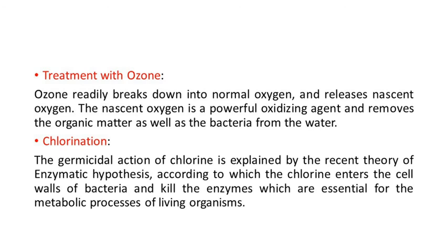And the opposite: suppose the water gets more than the required dose, it changes the taste and may change the odor of the water. Suppose your requirement is 2 ppm, and in that case you add 3 to 4 ppm, that is an excess of the 2 ppm dose. If you add an excess dose, it will change the taste of the water, sometimes the color of the water may also change, and it also changes the odor. So these are the various disadvantages of an excessive dose of chlorine.